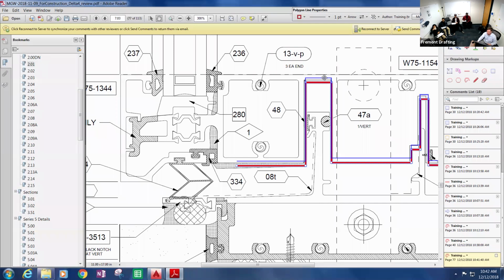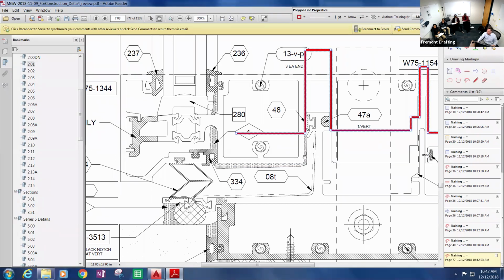And then let's say this floor doesn't move and the floor below moves, the chicken head is going to lower. I'm going to raise this one up just to show it, but we've got that same 3/4 of an inch right here so that we don't lose the engagement of our air seal, water seal gaskets. It has to stay in contact with the back of that horizontal, if the floor below that it's attached to moves but the one above doesn't.